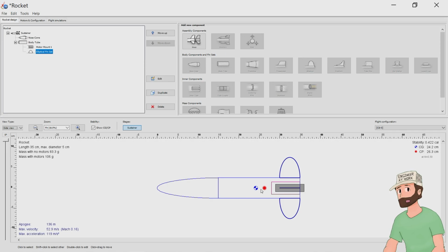Yeah, so there are a couple things we can do. You can see this is a general setup for a basic rocket. The big thing is what makes us go fast and high. We have a rocket motor, and that has a certain amount of weight, and it's made with gunpowder. As we burn that, we generate thrust that will fling us forward. As we're flying up through the sky, this red dot is more or less where all the aerodynamic forces act, you can imagine them all working as one arrow through here. That's not what actually is happening, but it's an approximation to make things easier to visualize and design. And up here, this little doohickey is our center of gravity.